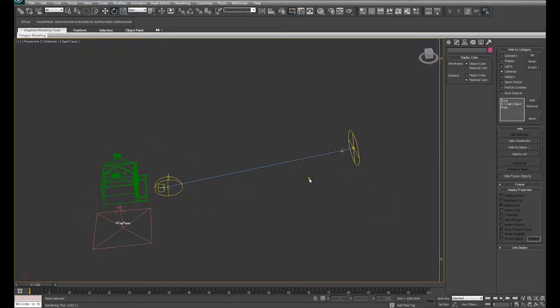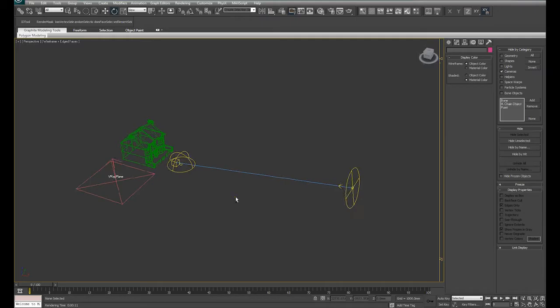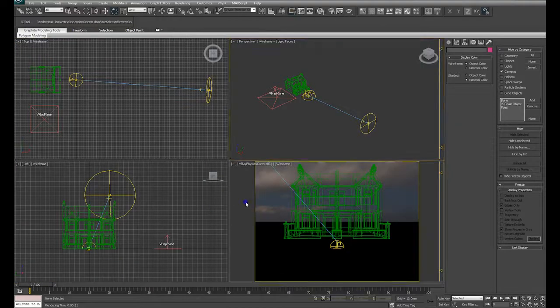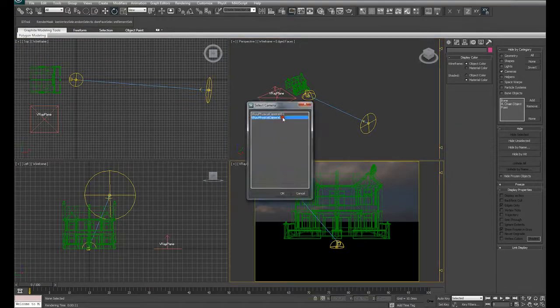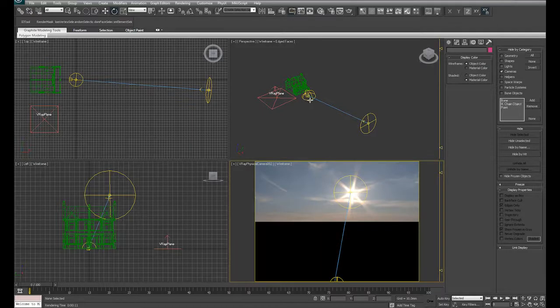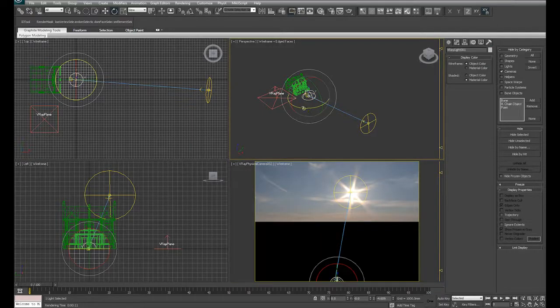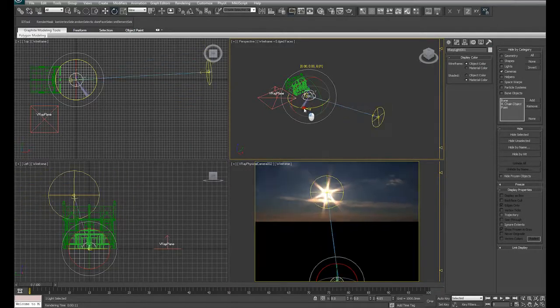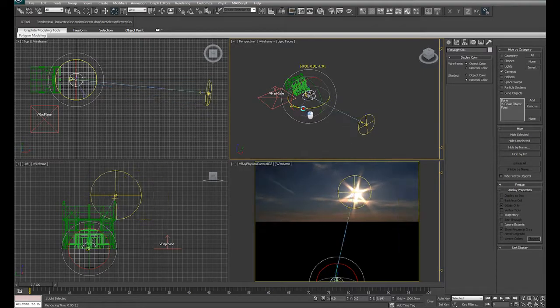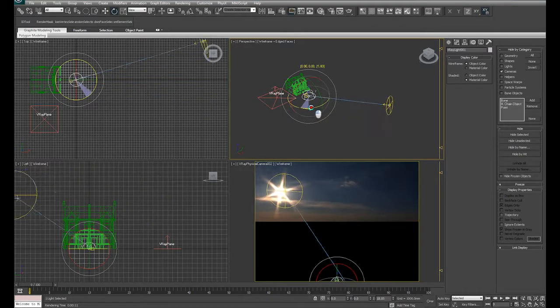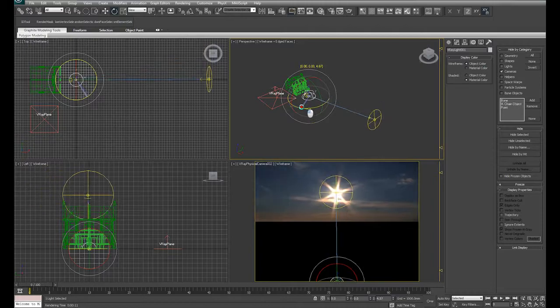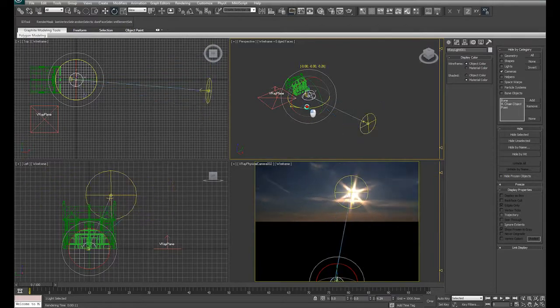At the same time, we want to introduce a VraySun to give us the very strong direct lighting and strong shadows, which you don't get from the HDRI. We'd also like to be able to link these two elements together so that when we select our dome light and rotate our dome light in order to adjust the direction of the sunlight on our scene, the V-Ray sunlight moves with our HDRI image.